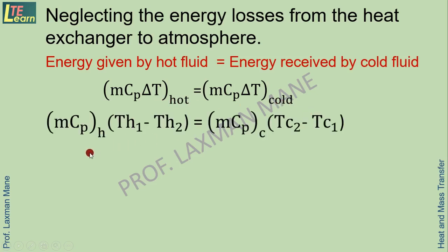It can be elaborated as m Cp, means mass into specific heat product for hot fluid, into temperature difference between inlet and outlet of hot fluid, is equal to m Cp product for cold fluid into temperature difference between outlet and inlet of cold fluid.